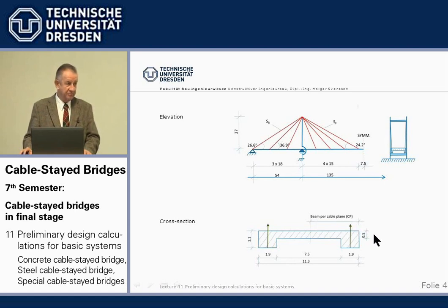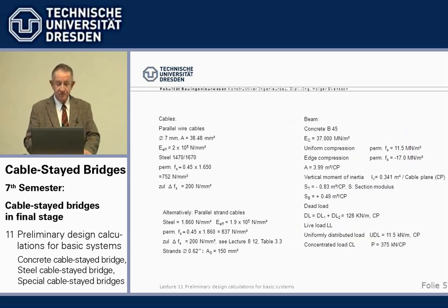It's from my experience over years that if you don't do that very rigidly, you very quickly end up with a factor 2, and you don't know was it for the whole bridge or the half bridge. So I recommend to you strictly per cable plane everything, then you avoid the mistake of the factor 2.